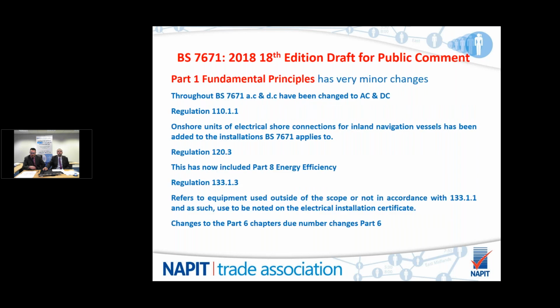Okay, so we're going to work through a few. So Part 1, fundamental principles, very minor changes. Throughout BS 7671, lowercase AC and DC have been changed to uppercase AC and DC in line with European documentation. Onshore units, electrical shore connections for inland navigation vessels has been added to the installations that BS 7671 applies to.